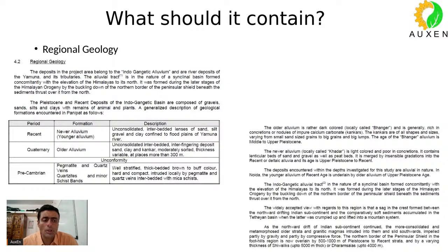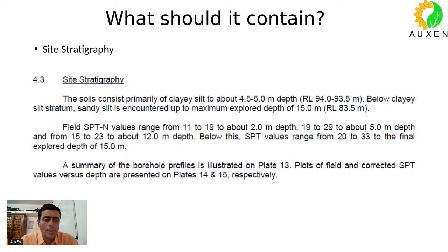So a good report should also give you the location of boreholes. It should give you some information about the geology. So what geological formations you will get on site, and other details about the geological features is important. You will see a section should always be there about the regional geology of your site. Then it should give you the site stratification.